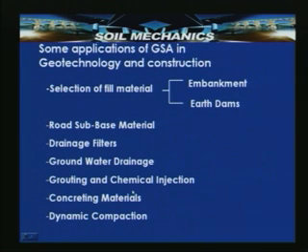So, to work this out, it is required to know about grain size analysis. In concreting materials, we have seen that in order to produce a denser concrete, you need to have a well graded mix, so that less cement or asphalt is consumed. The denser the concrete, the more resistant it is to weathering.